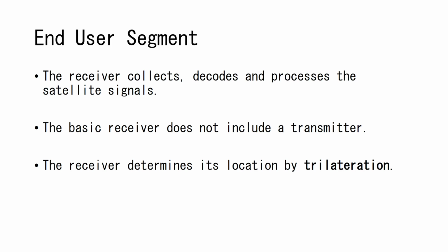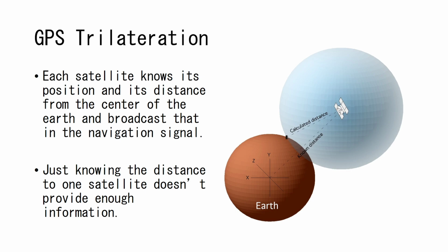And the method we use to do that is what is known as trilateration. Now in GPS, trilateration, as the term means, tri means three. Lateration, we're talking about lateral, so we're talking about distances. So we need at least three distances to be able to determine an unknown point. And the three distances we're going to be using are distances from our receiver to the satellites themselves.